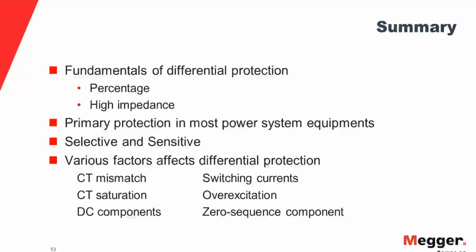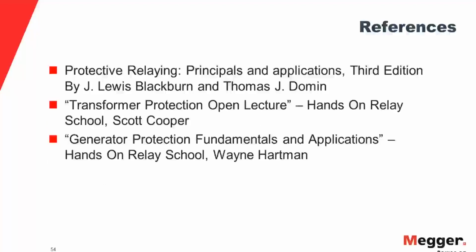So in summary, we talked about the fundamentals of differential protection. We covered the percentage differential and the high impedance differential. Percentage is where you incorporate slope, and high impedance is where you monitor the voltage.